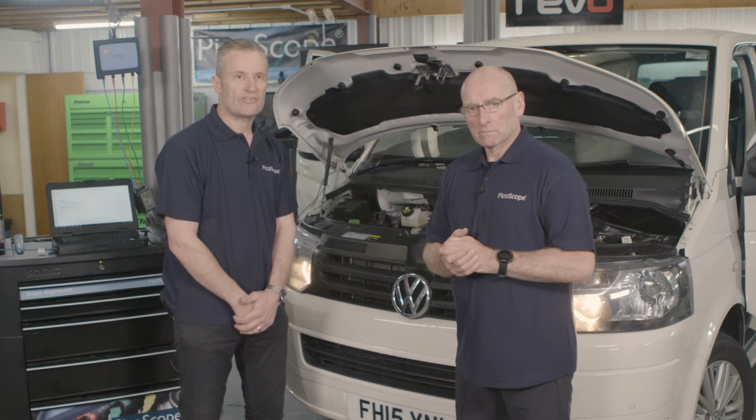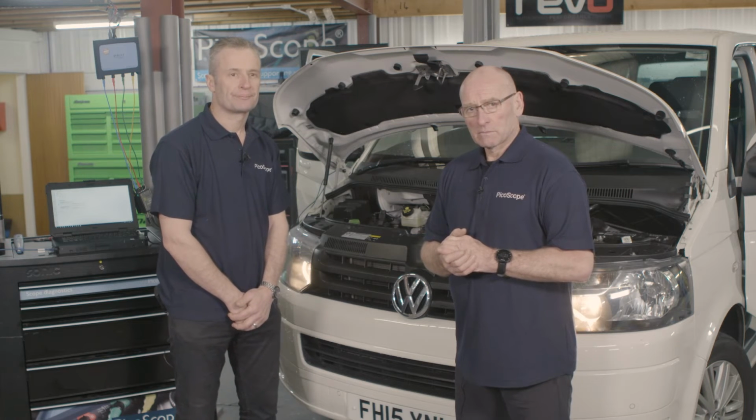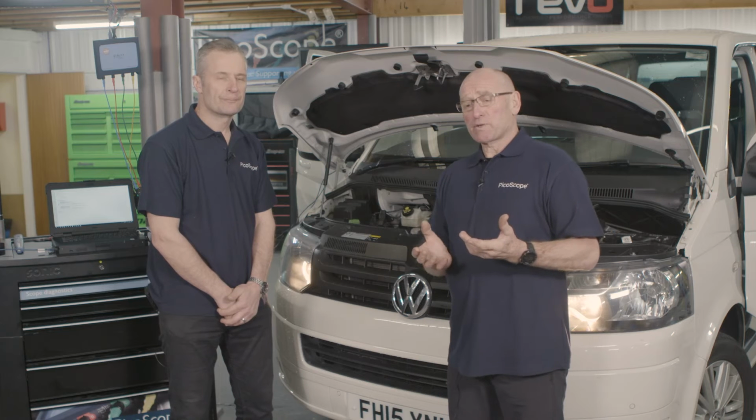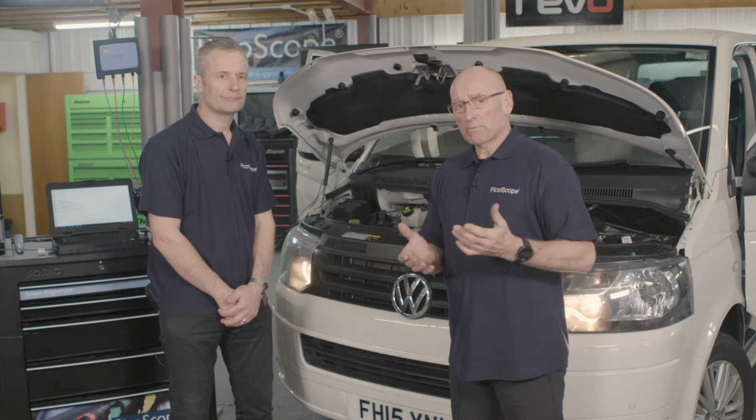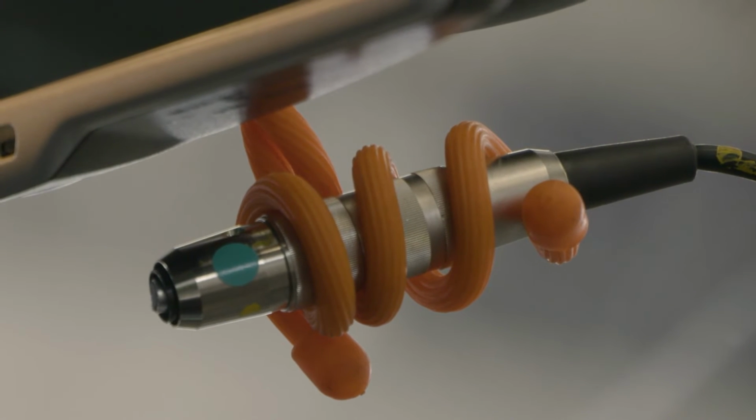Certainly this would be your choice of measurement for chasing a transmission whine, for example, or brake squeal, anything sort of above 200 hertz. So really this technique is for indiscriminate noises which really can't be easily identified to a particular component. Yep. Okay. So connection-wise, we've gone for 3-axis plus single channel. So still use one accelerometer measuring all 3 axes. But the additional channel now, channel D, is the microphone connected to the rear view mirror. So in a road test example, the microphone will detect all noises, but there's a specific noise we're chasing here, which is the noise generated from the imbalance in the cooling fan.